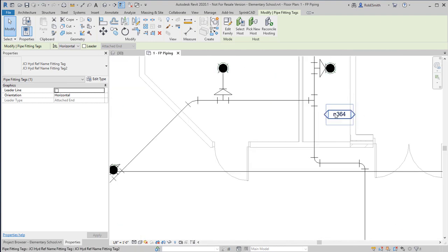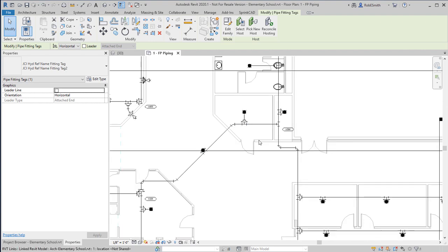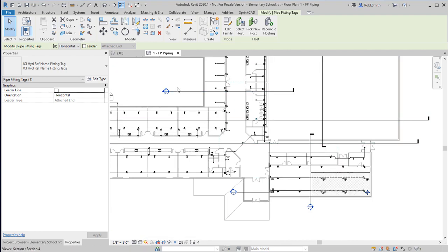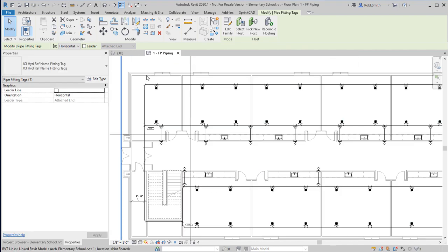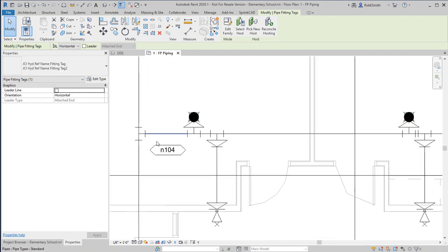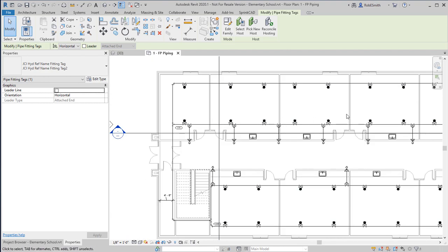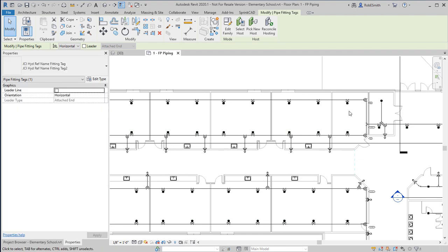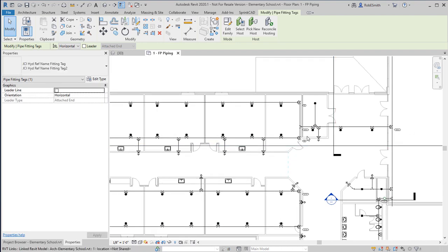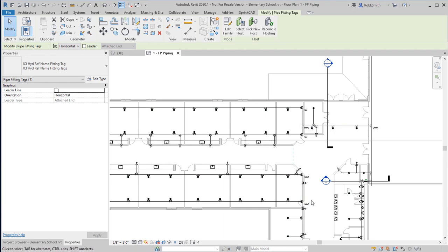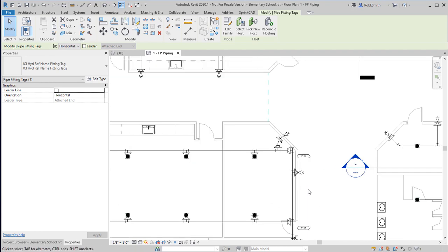Here's node 364 where the 45 gallons first split off to go off on the rest of this loop out here. At every junction point necessary, the program will give you this kind of data. The only time that data doesn't appear is if there's no hydraulic requirement according to NFPA 13 to represent that data on the plan. Any place where NFPA 13 specifies that a node needs to appear, you'll get them.